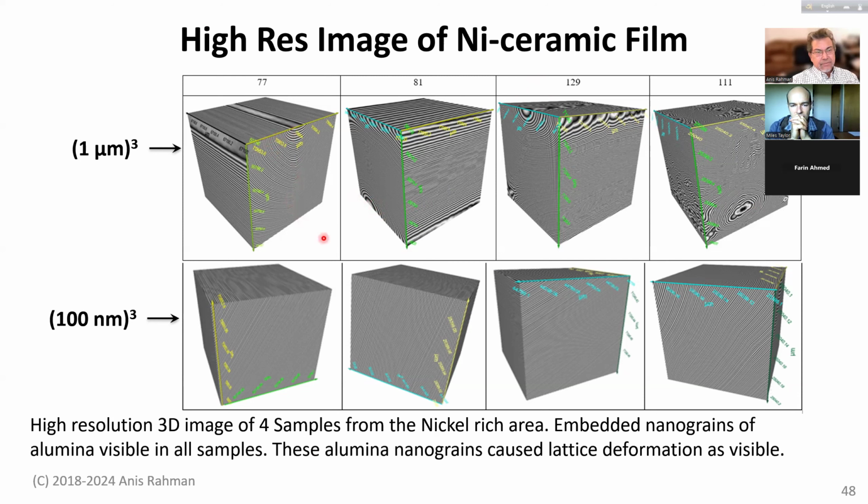Because at the interface, even though we wanted to look at pure nickel, we also captured that alumina particles got trapped in the metal, right? It's very useful information. And then this 1 cubic micron is further zoomed in at suitable places so that the inclusions are eliminated, not taken, because we want to see the lattice dilation: if the nickel lattice maintained its lattice plane separation or not.